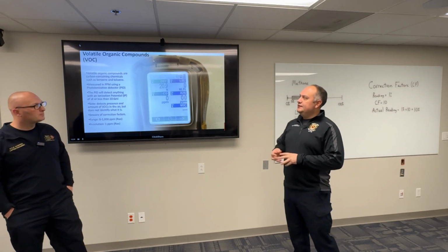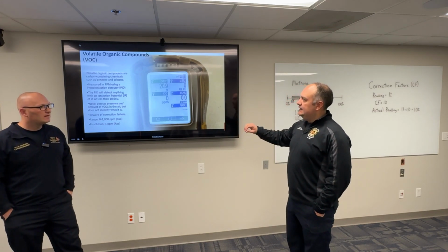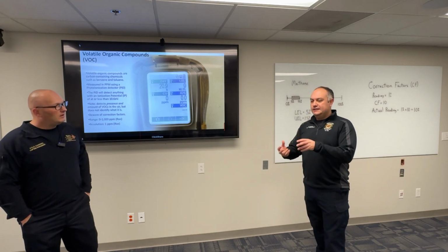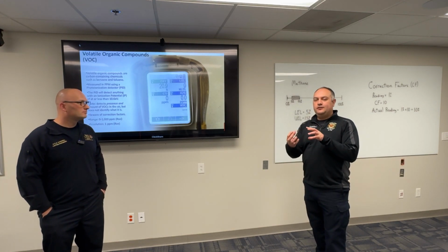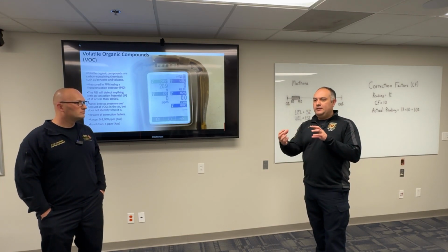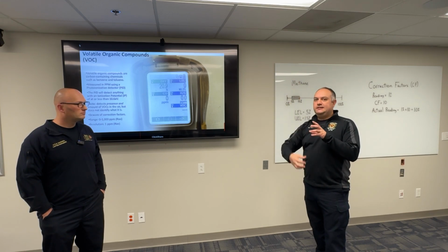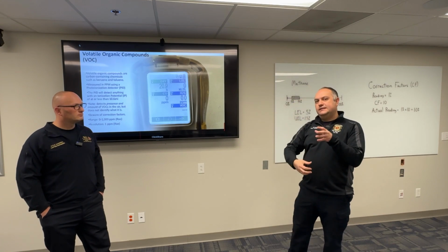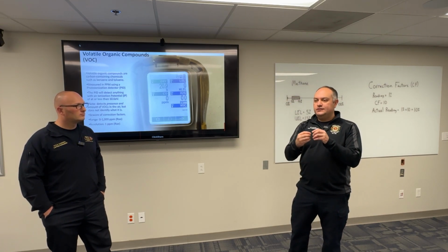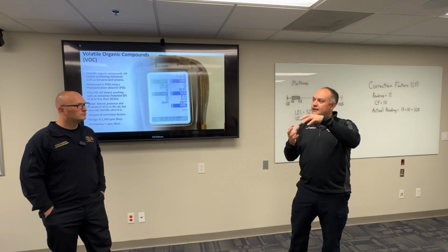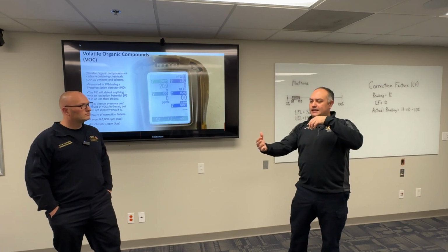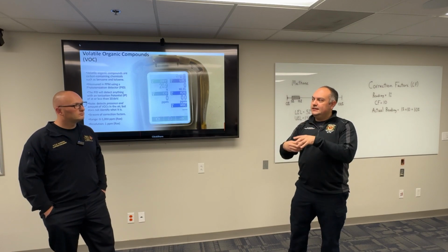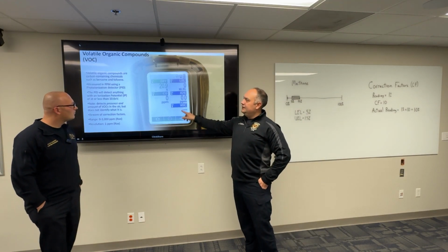Absolutely. So we're talking about a PID, which is called a photoionization detector. Basically it's a lamp inside of your machine. It's very small, and it applies a current and ionizes the air that's coming in. If we have some substance in the air that passes the light of this lamp and this energy, it breaks it apart so the other side of the sensor can see it. As soon as it exits, it goes right back together. But that reading that it senses is going to give you the number right here on your VOC.